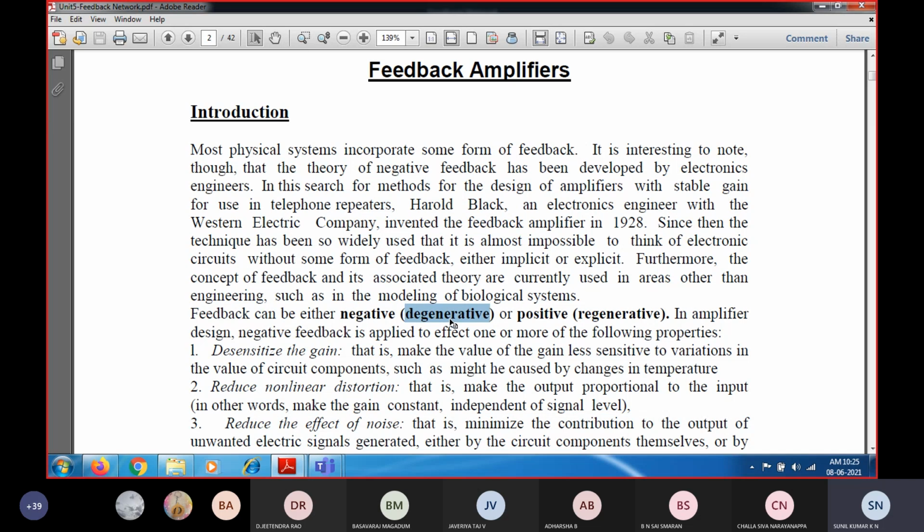At the same time, source resistance has been added with respect to the source. In the bias networking problem, we have seen that this resistance RS or resistance RE acts like a negative feedback, and it is called a degenerative resistance.